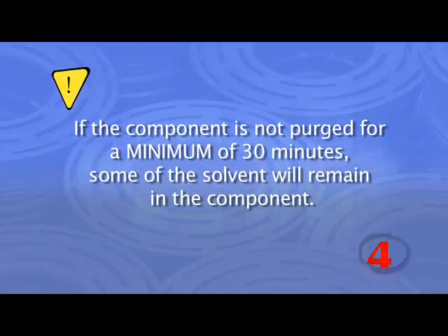If the component is not purged with dry shop air for a minimum of 30 minutes, some of the solvent that is mixed with the dirty oil will remain in the component. Even though the system will be evacuated under a vacuum, the solvent and oil mixture will not vaporize.